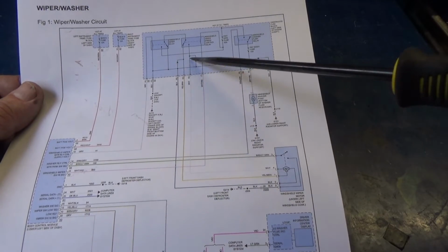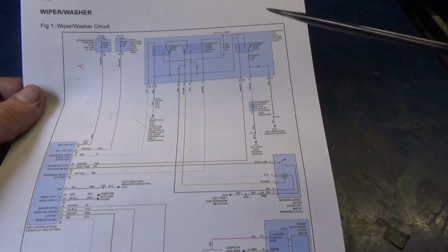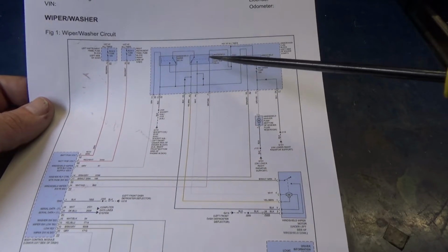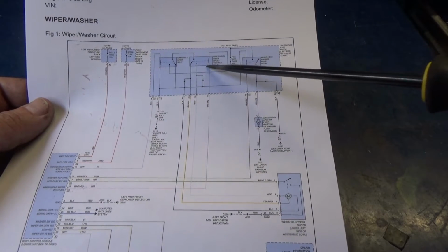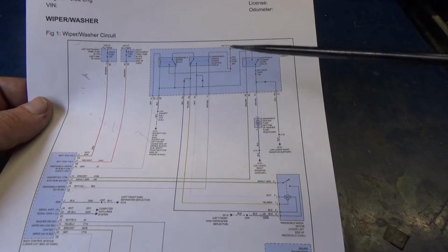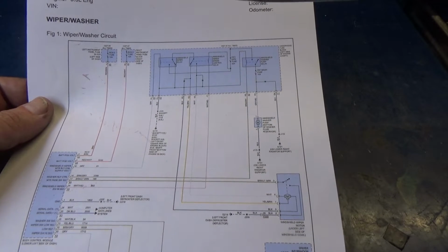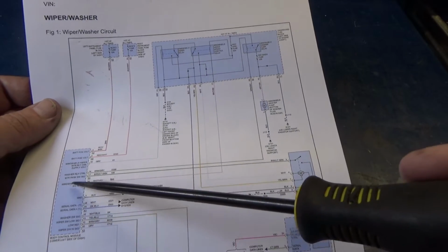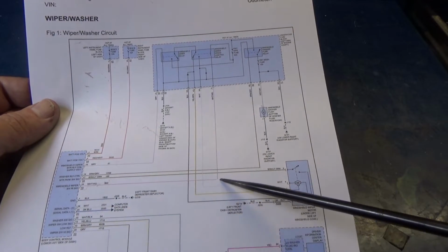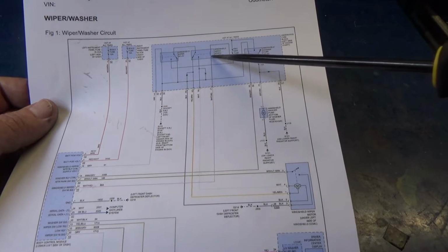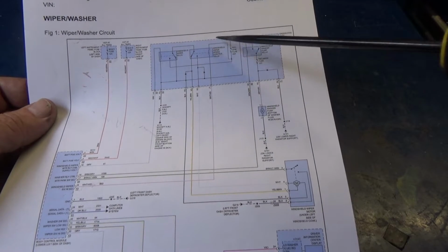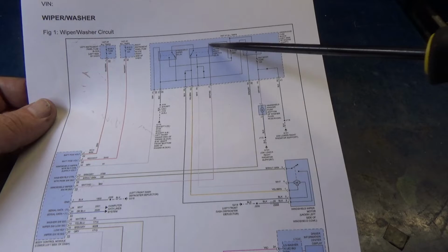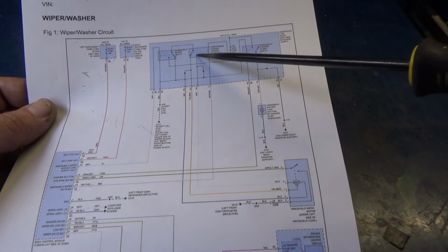So how's it work? Which is the circuit that's not working currently on this truck. Whenever this relay energizes, so when you go to the high speed detent on your multifunction switch, the BCM sends a ground to this coil, because it's always supplied with this power right here. Contacts are going to slam over.